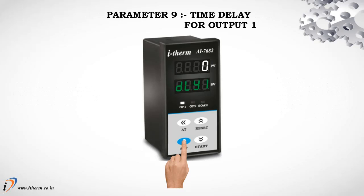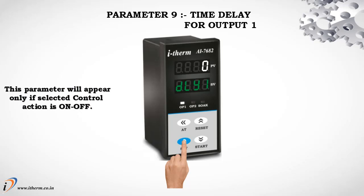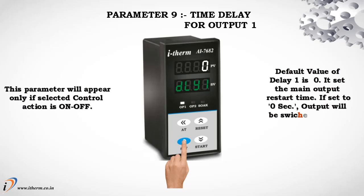Parameter 9, Time Delay for output 1. This parameter will appear only if selected control action is on-off. Default value of delay 1 is 0. It sets the main output restart time. If set to 0 second, output will be switched without delay.